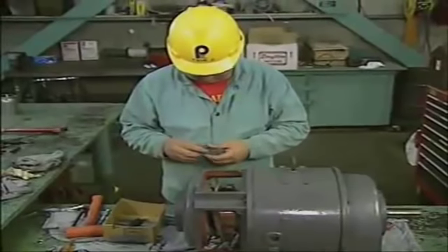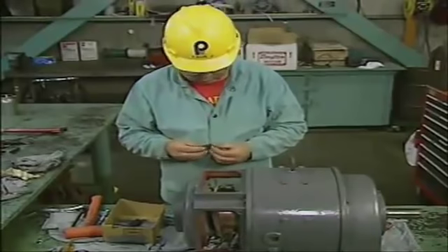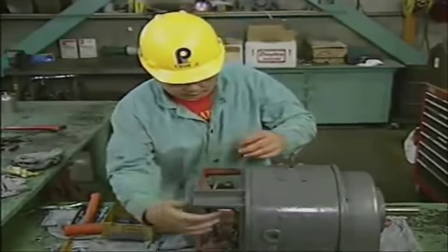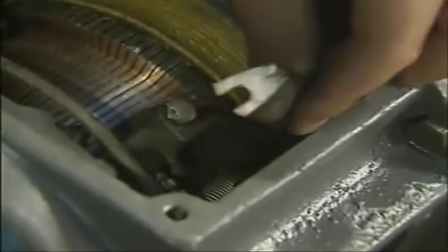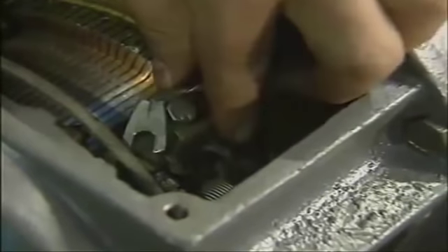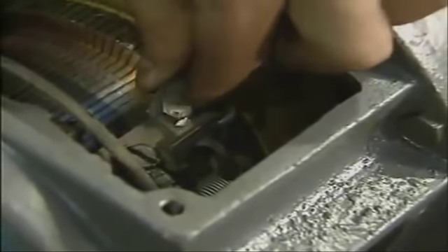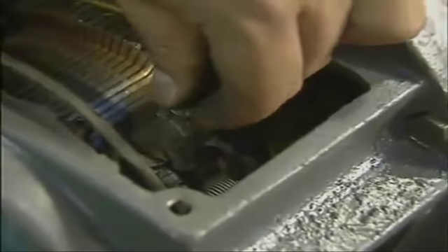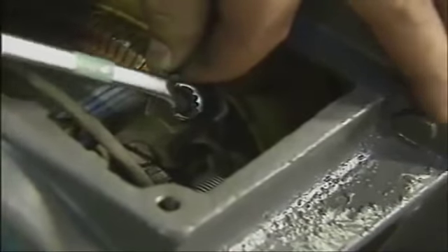If the shaft does turn freely, the next step is to connect the field coil leads to the brush rigging, making sure that the connections are clean and tight. Each brush should then be checked again to make sure that it's in good condition, and then placed in its brush holder. The brush tensioning devices should be set. And finally, the brush pigtail should be connected to the rigging. This procedure is repeated for all of the motor's brushes.